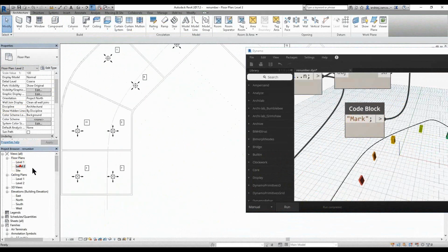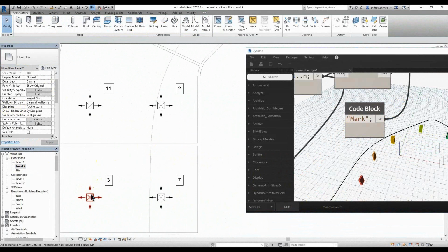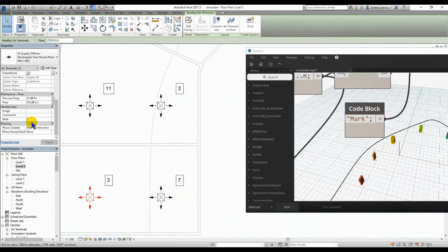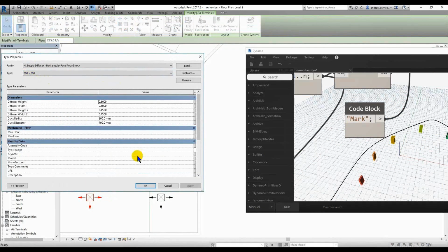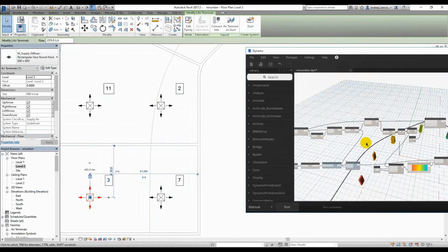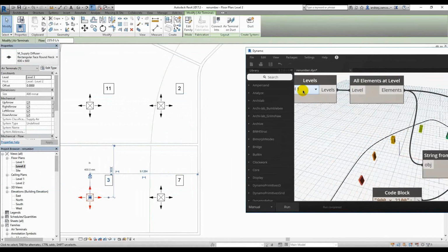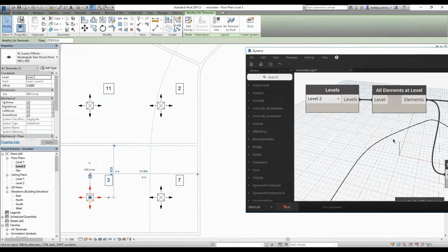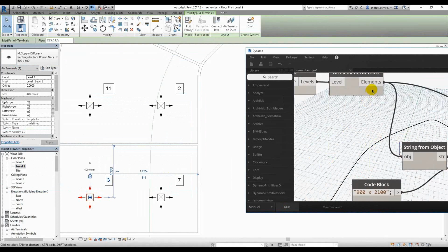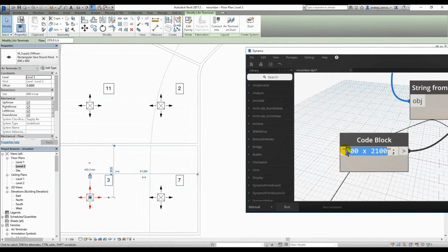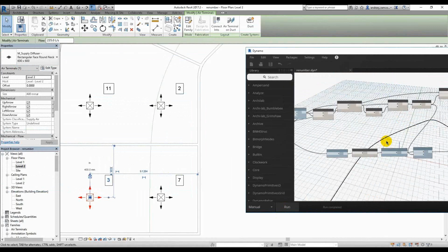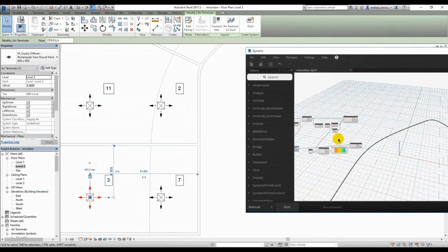And by the way, this curve doesn't even have to intersect with these elements. In this example, I have some air diffusers, some MEP mechanical elements, and their numbering is also kind of random. It can be an air diffuser, a fire sprinkler, any element. What I need to do is just provide some criteria to Dynamo. In this case, I just need to draw that curve in a way that satisfies me in terms of renumbering order.